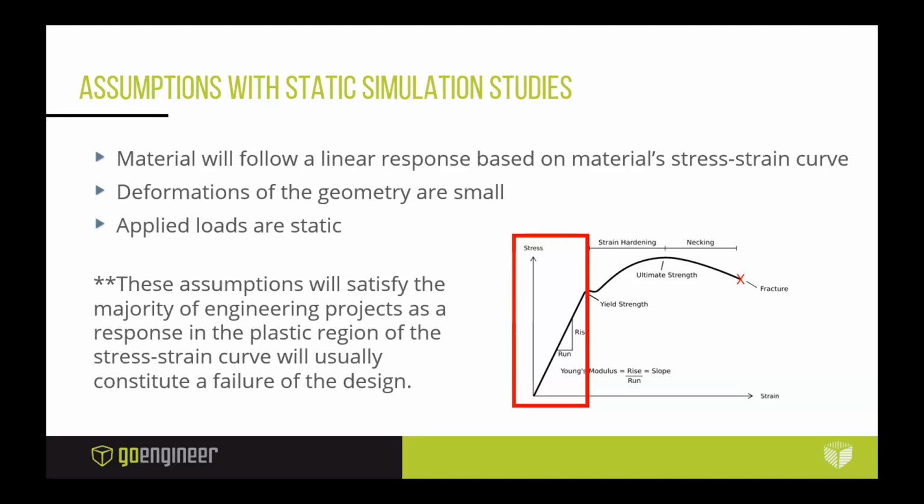Now, that can be subjective, right? So what is a small displacement? Luckily for us, when we hit that run button on a static study, the software will give us a message. You guys have probably seen it if you've used the tool. It says something about excessive displacements were found, and it gives you a bunch of verbiage, right? We just say, no, get rid of that, click cancel, right?